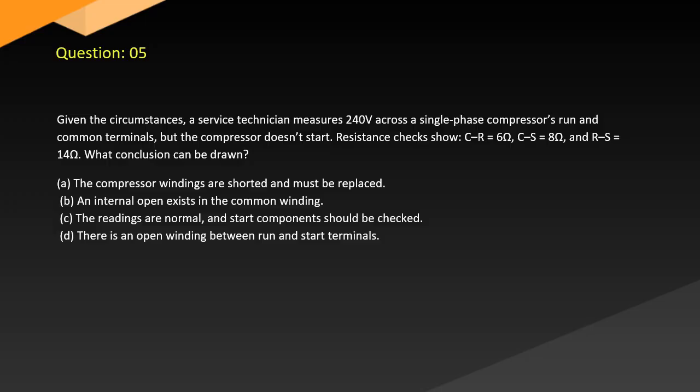Question 5. Given the circumstances, a service technician measures 240 volts across the common terminals of a single-phase compressor, but the compressor doesn't start. Resistance checks show C-R equals 60, C-S equals 80, and R-S equals 14. What conclusion can be drawn?